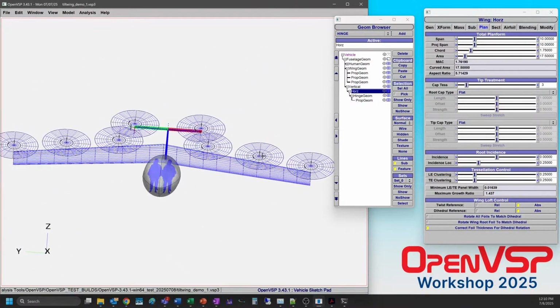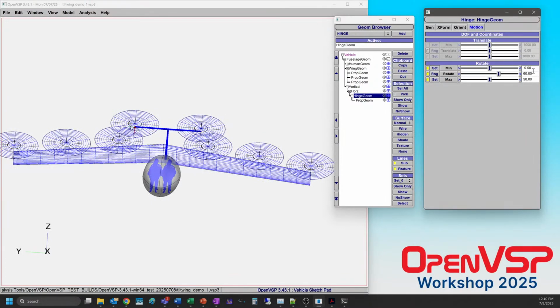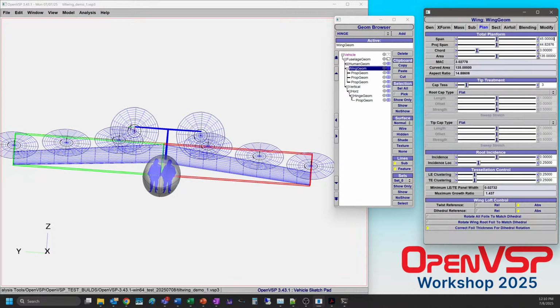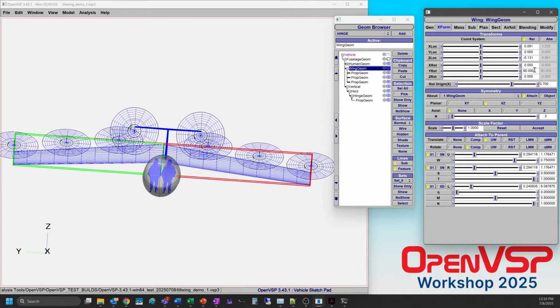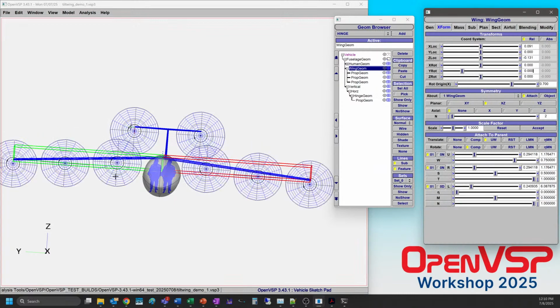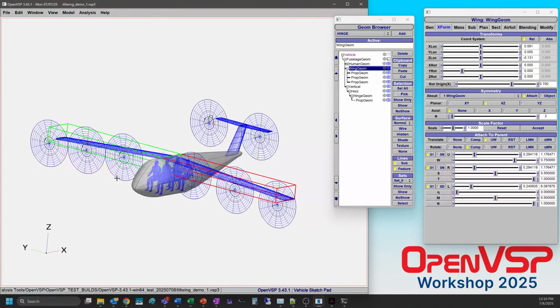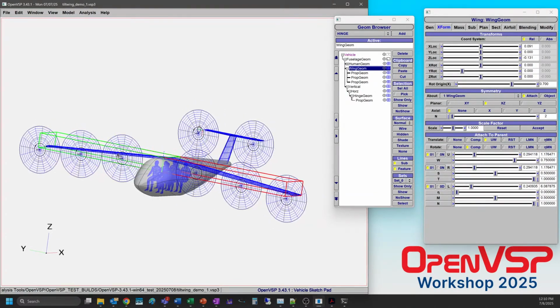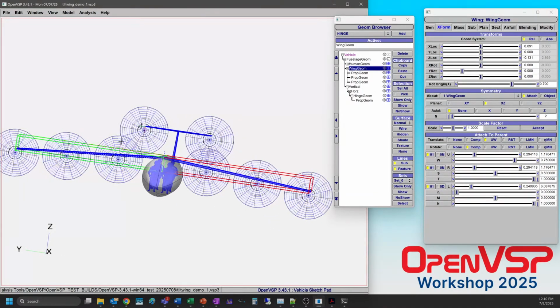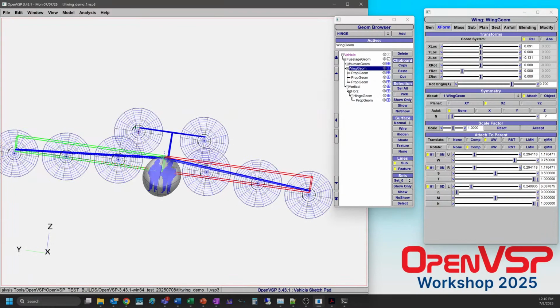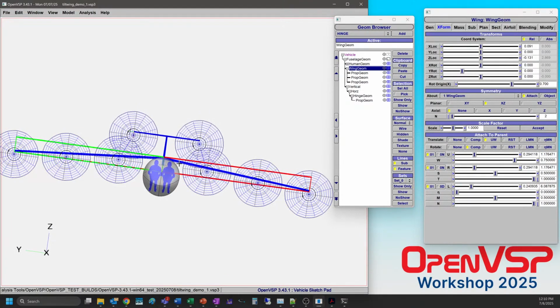Now, one of the things we might want to watch out for, if we set our rotation of the prop rotors back to 0, all right, set our wing back to 0 in our transform tab. If we're looking at it from the front, the prop rotors in the back, which are trying to either provide thrust, they're trying to lift, they're doing other things, are going to be influenced by these 2 rotors in the front. So they need to be offset a little bit.